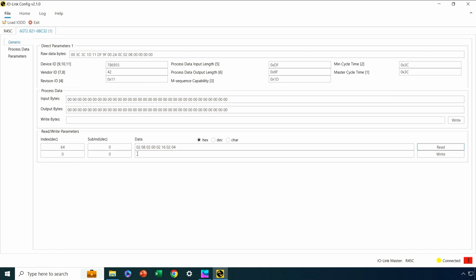So basically what I did was I just typed in the values that I needed, like this, 02, 08, 02, just copied them straight across. Of course, changing the one that I needed changing. It was 4 when I first did the read on the device. Press the write, and it writes this data. I read it back just to verify everything changed, and we were good to go. So that was a step I did have to take on this particular reader to change that 1 parameter. Okay, now once I had done that, then really that was all the configuration that was required in my example.